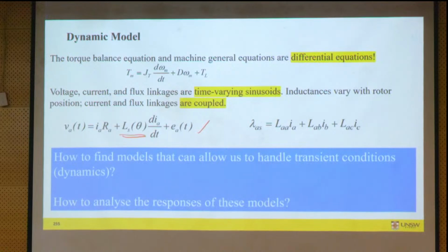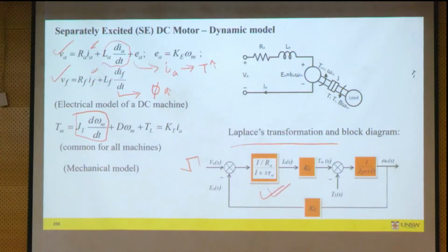Torque from the motor is actually a function of current and flux, and they are coupled. This flux is the resultant stator flux linkage, which includes the PM flux as well as the current flux. So again they are coupled, and separation is not as easy as it was in the DC motor.